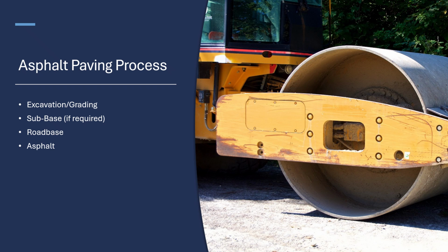Asphalt is going to come in usually some sort of dump truck. There's multiple kinds. The important thing to remember is that asphalt comes in trucks that are measured in tons. And so a single truck usually holds about 17 tons. It could hold more. If your truck has arms on it, that usually means that it holds 21 tons. And then you could have trucks with extra trailers. Those are called truck and pups or doubles and then triples. And that's going to hold anywhere from 17 to 21 tons of asphalt.